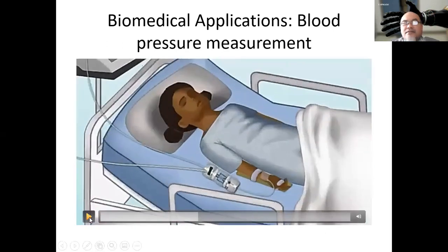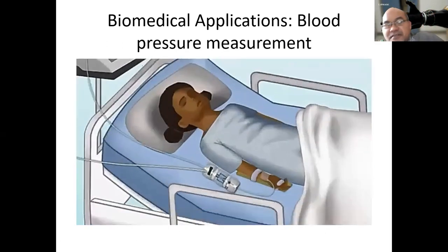In a Wheatstone bridge, this is usually done by zeroing the output voltage between the 4 arms of the bridge. That's why usually in the reference arm, you put a potentiometer, so that at the initial condition, when there is no stimulus, you tune that potentiometer such that the output of the Wheatstone bridge is 0.